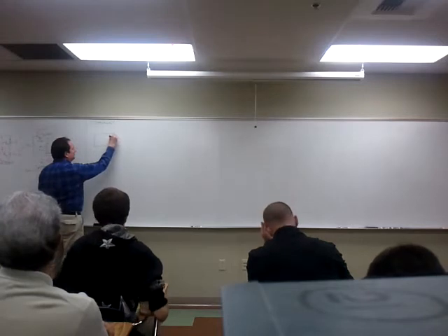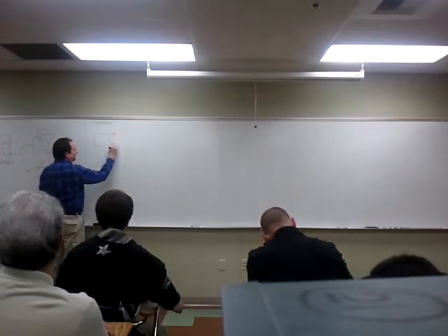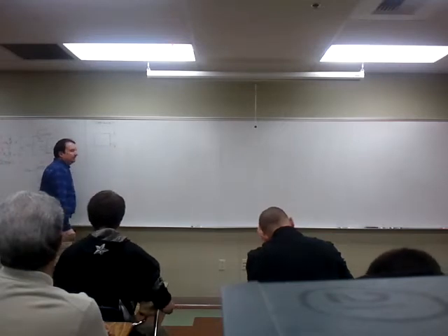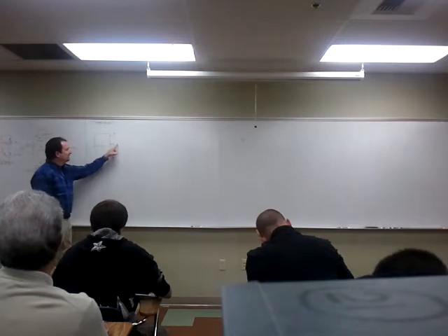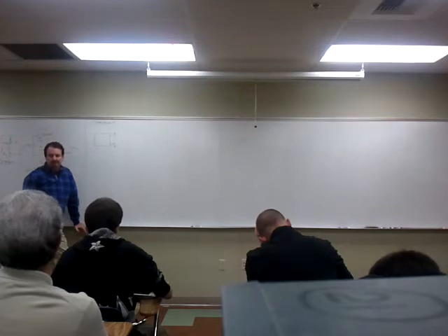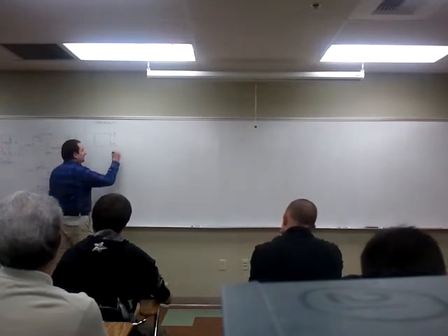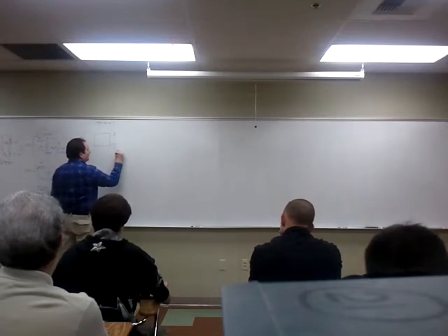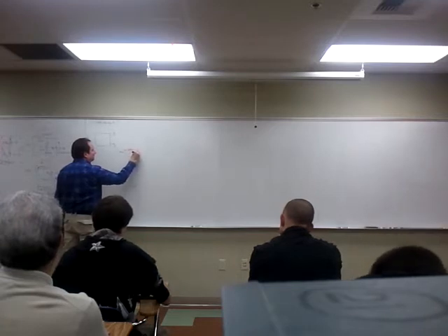If you had 2 points coming out of a circuit across any element in a circuit, what can I measure between these 2 points? Or consider this, a black box. You can't see the circuitry inside. They have 2 terminals coming out of this black box. What could I measure? Well, one thing I could measure is the voltage from A to B. That would be the open circuit output voltage.